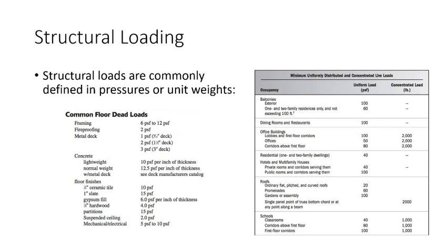If it's a 6-inch slab, do you actually design for 6 inches, or do you design for maybe 6 1/4 to account for a little bit of additional material or overpouring or whatnot? So that's something that happens on bridges. In fact, when you cast bridge decks, you actually purposefully overcast it a little bit for a couple of reasons. One, maybe they'll grind it down later to set deck elevation, or two, wear and tear over the top.